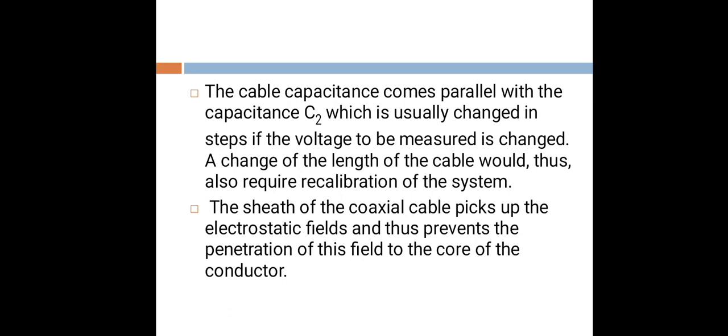A change of the length of the cable would thus also require recalibration of the system. The sheath of the coaxial cable picks up the electrostatic field and thus prevents the penetration of this field to the core of the conductor.